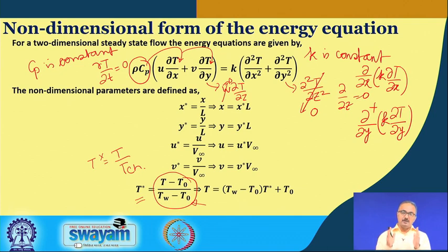If you apply this type of non-dimensionalization, defining T star equal to T minus Tc divided by Th minus Tc, then T varies between Tc and Th, so T star varies between 0 and 1. It is normalized. Otherwise, if we cannot ascertain that the temperature will be bounded by some values, then even if we define it like this, it does not ensure that we obtain a normalized non-dimensional temperature. So, this should be clearly understood.